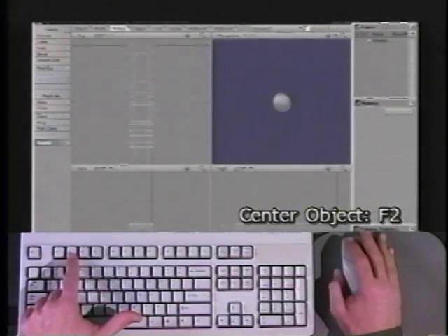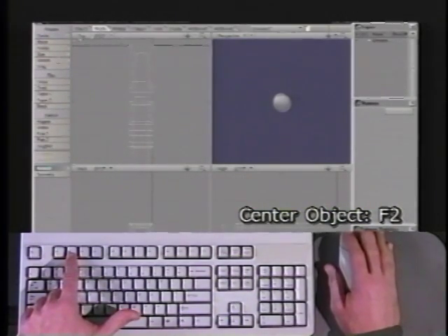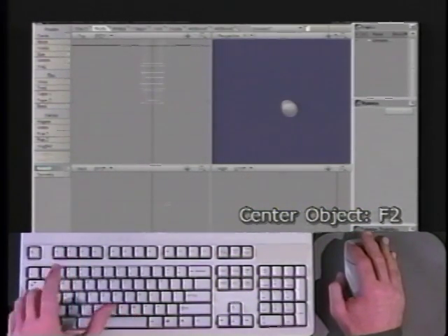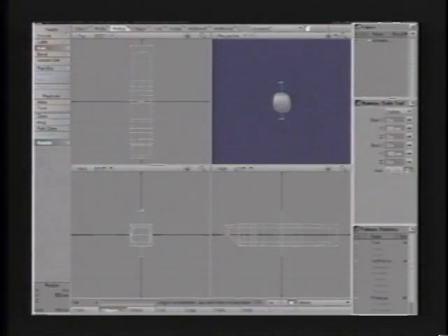So to do that, once again, we go to Knife. First of all, I'm going to center the model. We can do that with our keyboard equivalent of F2. On the screen, it's under Modify, Center, but use F2 and get used to that. It's easy to do. Okay. Multiply, Knife. And I'll just drag this up right along the 0 axis.